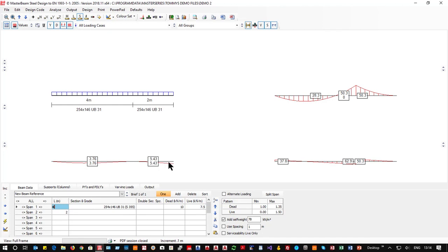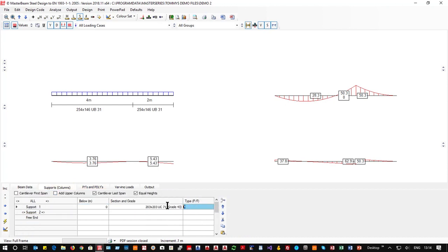And this is one of the most important things to understand about cantilevers: there's very, very rarely an encastre cantilever that has full fixity. If I say that my supports weren't pinned but fixed everywhere, then you're going to get fixed end moment here and here, and you then get just that deflection from the fixed end moment. Whereas you were getting a bit of pre-rotation due to this when I am in pin, and now that's dropping down, so it's actually a lesser deflection.